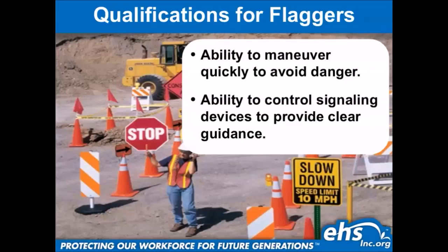Because after a while, staring into traffic, guys, you start thinking about who's playing tonight. Did I pay that last bill? People get random thoughts for some reason. So pay attention to your flaggers and swap them out as necessary.